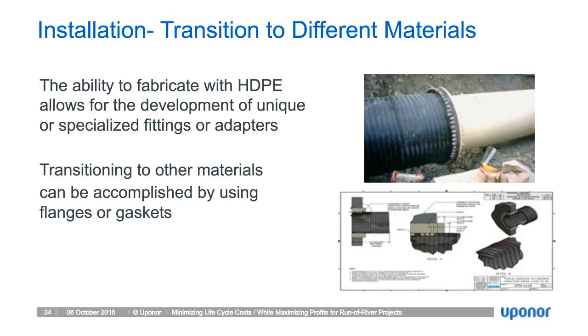We can transition to different materials, and the reason you want to do that in power projects especially is because we'll pressure out at roughly 22.5 psi, but that doesn't stop us from being involved in penstocks because we can flange up to steel after that. The advantage of using Whalite in this fashion is that it's cost effective, it's pretty much maintenance free, it's light, and easy to handle. You don't have to worry about any types of coatings. And so contractors love it, owners love it because of those benefits. And then when we pressure out, you can move on to steel after that.